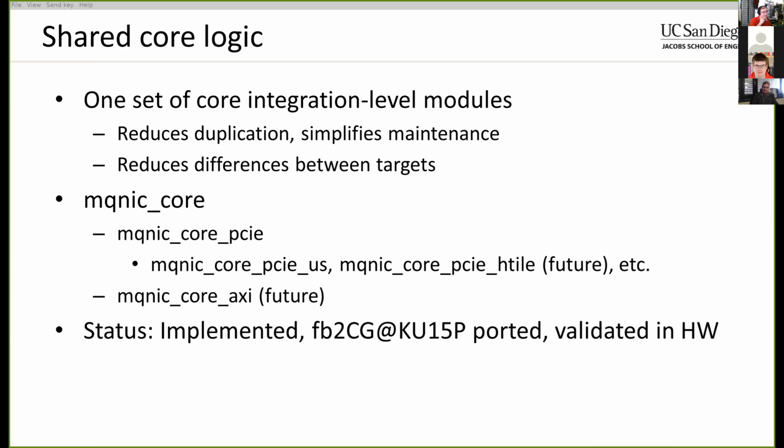The other reason for doing that is eventually what we're going to have to do with the shared interface data path is have a big, shared TX and shared RX module, which does data width adaptation and a few other things and handles PFC pause frames and whatnot. And all that's going to be synchronous. So we need to have a separate large synchronous FIFO and small asynchronous FIFO. So by putting all of that in the shared logic, it means I can do all that shuffling and change all those settings all in one place instead of having this strewn across the hierarchy.